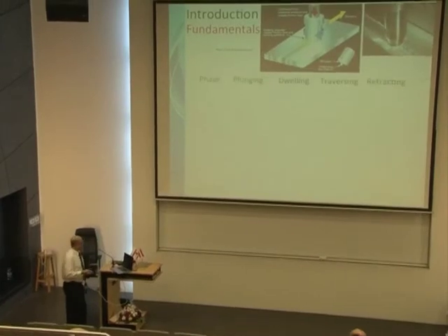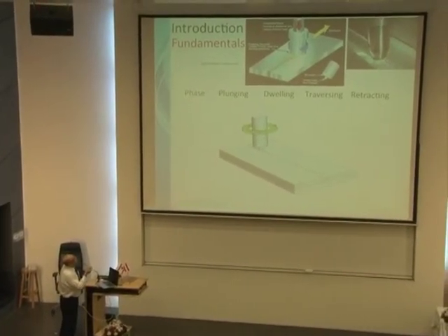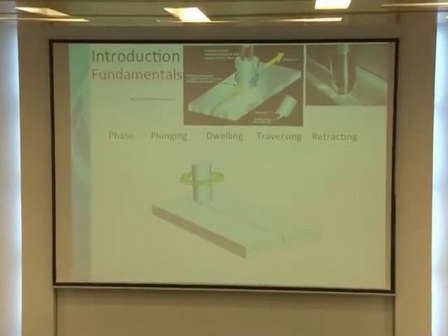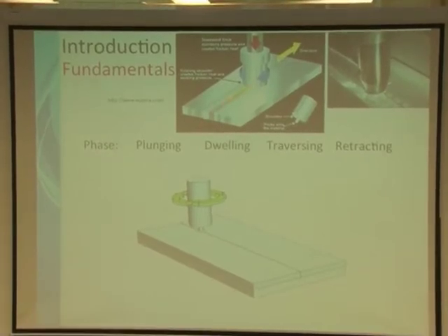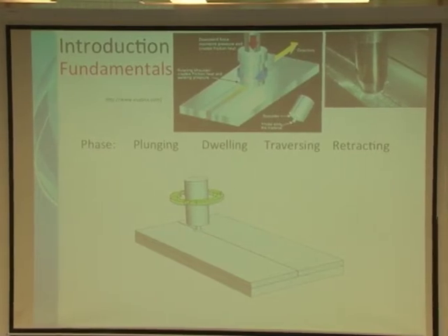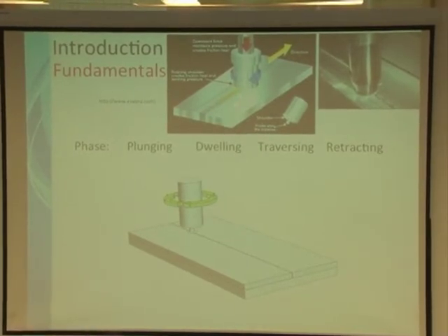So how does this work? If you look at the basics of this, you see a pinned tool with a big shoulder. As that spindle spins and rotates, the tool is being fed almost similar to machining. So a lot of spindle speed and slow tool feed. What happens is the rubbing of the shoulder against the workpiece metal will create friction and thus heat, while there is a lot of thrust force from the top down, which keeps the pressure in contact.